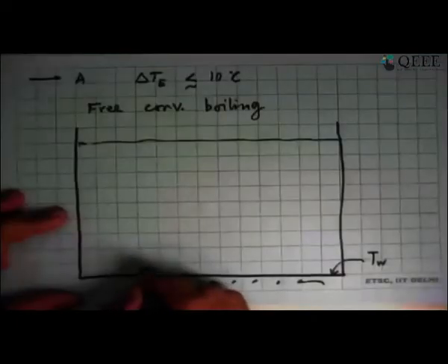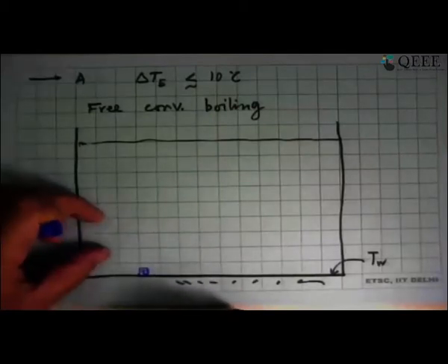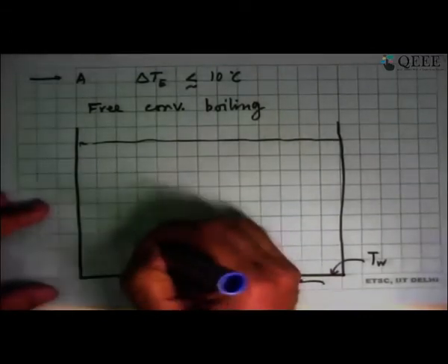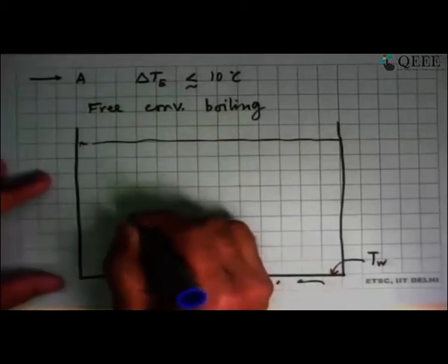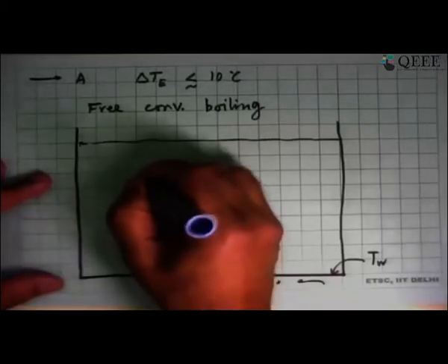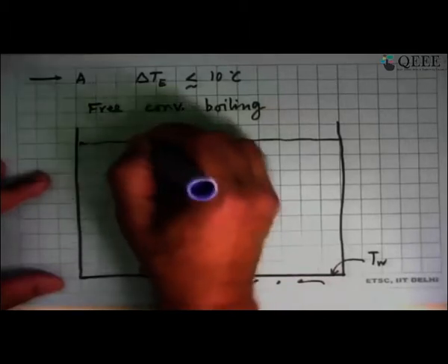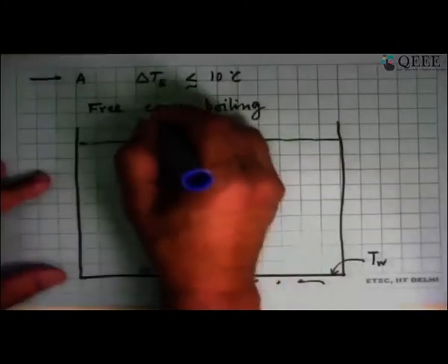We have to go to non-equilibrium thermodynamics in some sense, where a little bit of fluid over here, a fluid element, its temperature goes slightly above the saturation temperature, but it does not change phase. This phenomenon is not equilibrium, it is a non-equilibrium phenomenon. It rises up, and as the pressure keeps decreasing, its volume increases slightly. Then it rises up by buoyancy. Remember, this is buoyancy again. It comes up here, and finally it comes to the surface, where the phase change takes place, and you have saturated vapor coming up.